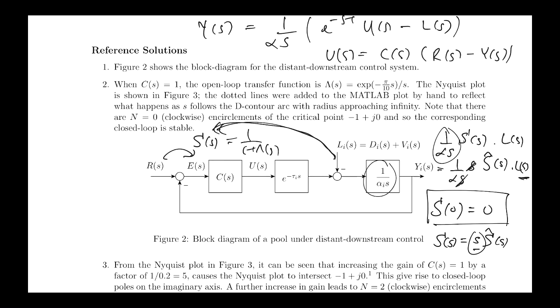Okay, so that's why we can get 0 steady state error for step changes in the reference, but not step changes in the load.